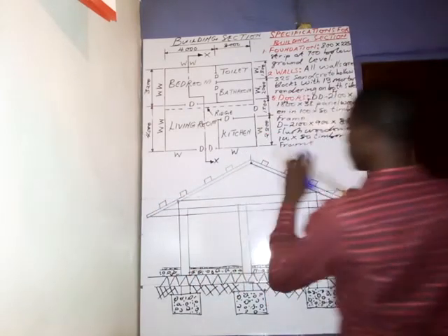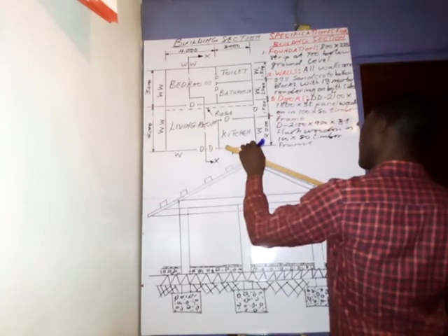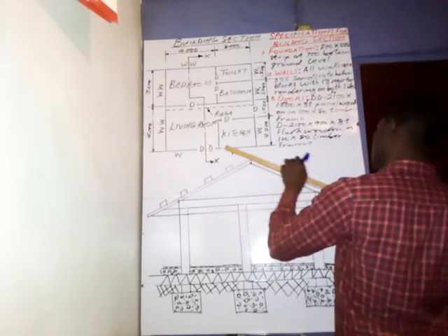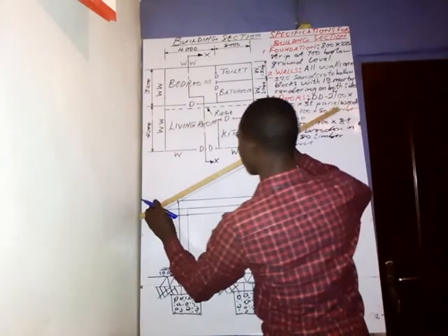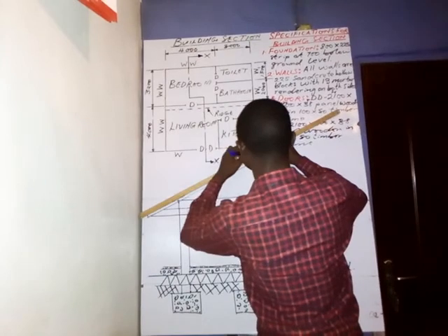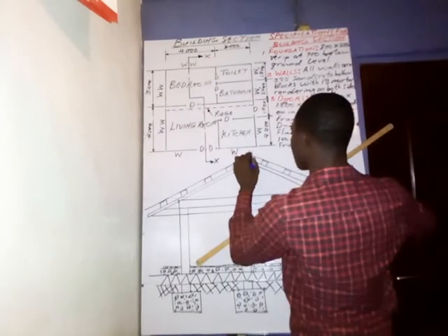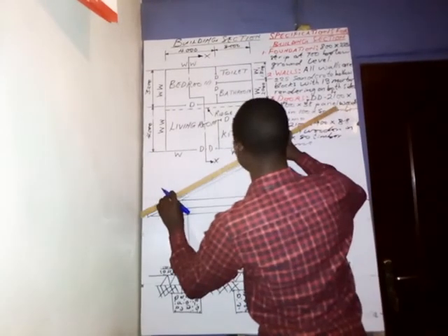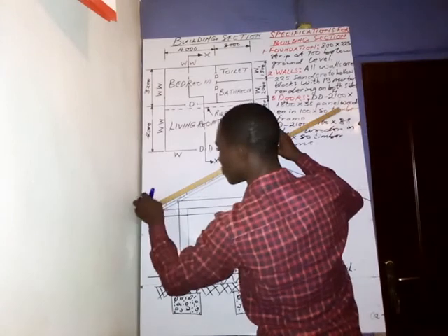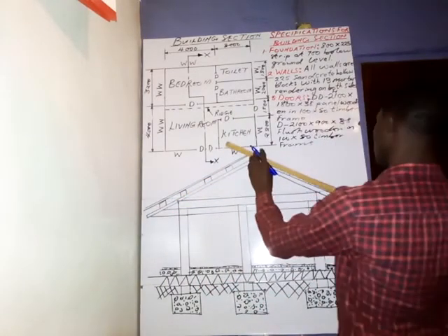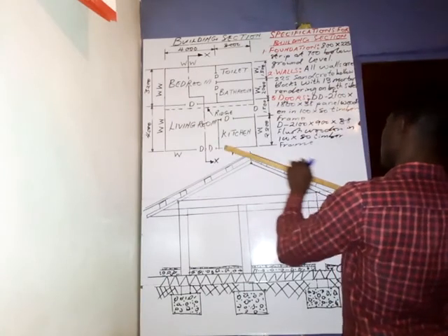Alright, so then the next thing I'm going to put here is the roofing sheet. The roofing sheet will be laid on the purlin, as you can see here. Now also produce it to this side like this. The roofing sheet has its own thickness. Just take like 1 mm or 2 mm and draw. And also, you draw this.